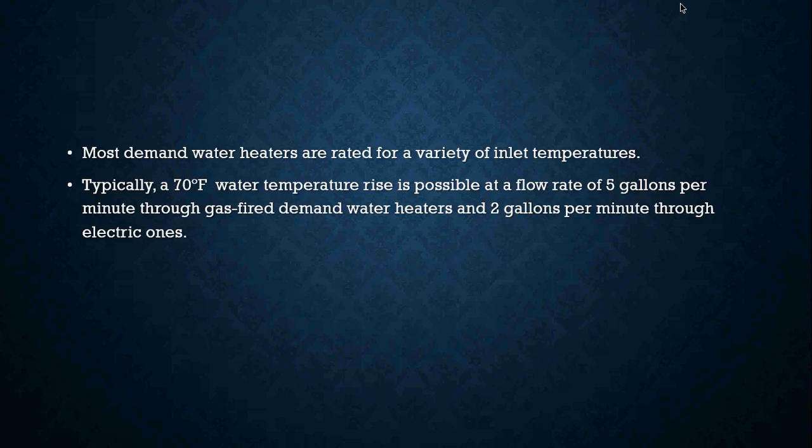If I'm moving too much water too fast across those heat coils, I'm not going to be able to deliver the correct amount of heat and the correct amount of water temperature to my faucets and my appliances in an efficient amount of time.